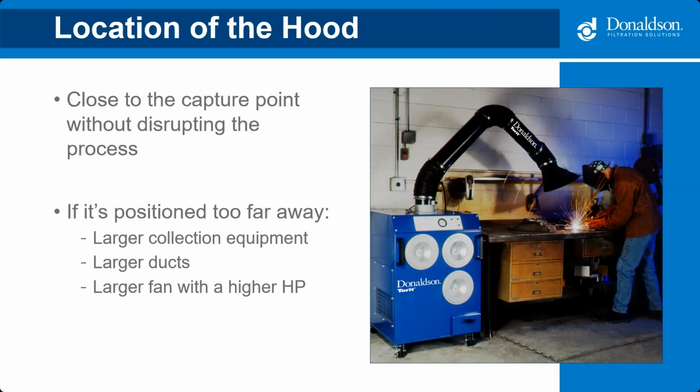And of course, more air means larger collection equipment, larger ducts, larger fan, higher horsepower, all of which adds to capital and operational costs. In the picture here is a portable weld fume collector. The hood is positioned close enough to capture the fume and pull it away from the operator's breathing zone, but far enough away to not disrupt him or the process.